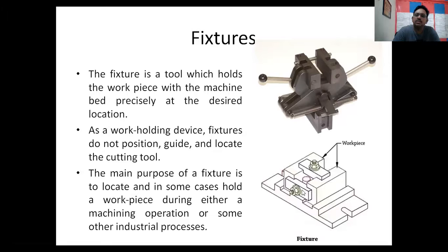It should hold. So I have some fixture here. See, the entire setup is the fixture. You have a base plate, and on that you have inserted the workpieces, and also with the help of these two things, the bolt and nut mechanism and T-slots, you have fixed those things so that the workpiece will not move. So firmly they are there.